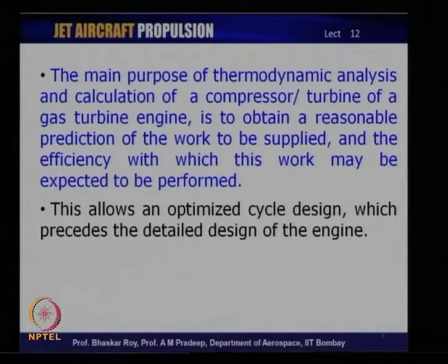One of the reasons I said that we would need to analyze the compressors and, of course, later on turbines through thermodynamic means is because they are part of the heat engine and they need to be subject to scrutiny under the thermodynamic matrix. And if we can show that they are amenable to fundamental thermodynamic rules and laws, then it is possible to provide a prediction mechanism of the amount of work they are doing, the amount of work that is transferred between turbine and compressor, and the efficiency with which this work is being transferred or done.